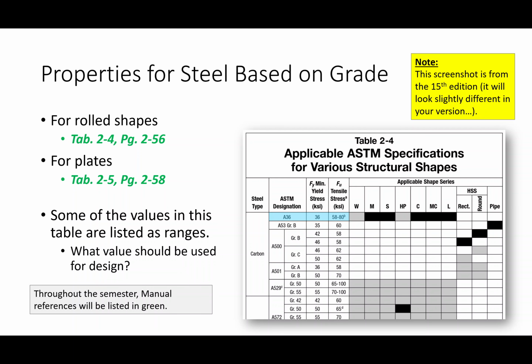So I'll tell you actually where the range comes from, and it actually comes from ductility, okay? So the thing about material behavior is that if you start increasing its strength, you have a tendency to decrease its ductility, okay? So back in 1994, there was a major earthquake, the Northridge earthquake. You can look it up. At the time before the earthquake, we were telling, and I say we, I mean the steel industry, was telling engineers that you needed to detail structures a certain way and that moment frames were really the best way of detailing structures in seismic zones.